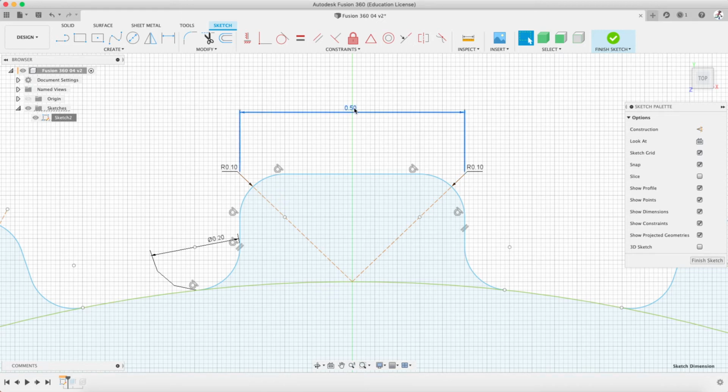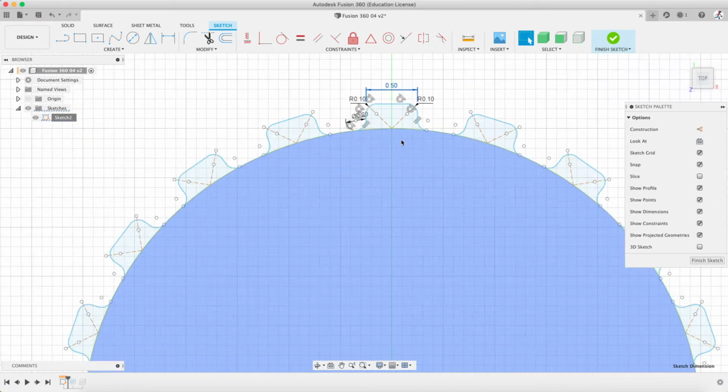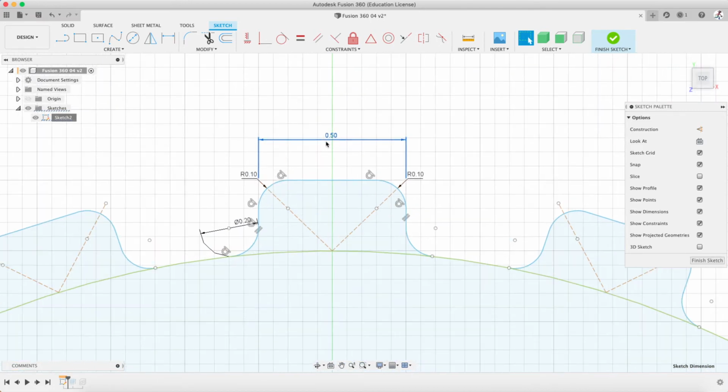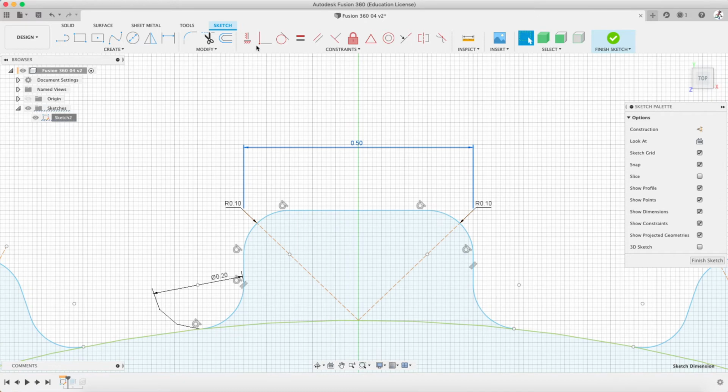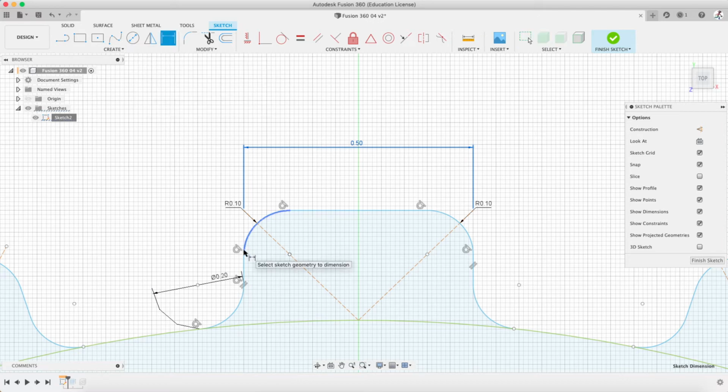Now here's where we're going to be using parameters. These are already set up. They are ready to go, but we really want to now assign these to the parameter itself. And we're going to have to redo all of these. So I might just pause the video and fix that. But what we'll do is, on these sizes, if you don't have them, one quick backtrack here is to get sketch dimensions. You can actually create a sketch dimension.